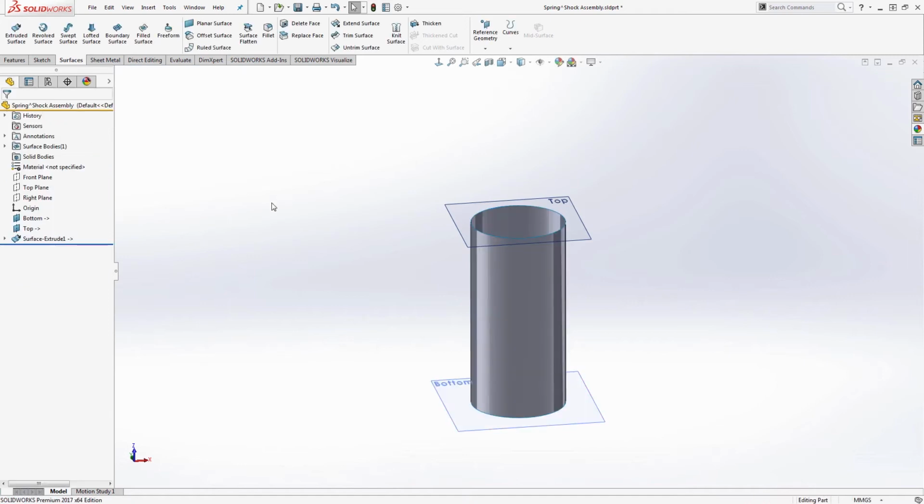Now at this point, it still doesn't look like we've done much of anything because we haven't. But what we have created is this adjustable height cylinder that will move up and down and scale. And we can intersect this with something that will give us some kind of reference that will shift up and down. And that's exactly what we'll do here. In order to create this geometry, I'll actually create a sweep that creates the helix itself. This is really the crux at this point of the surfacing trick. So let's create a couple of sketches here in order to make this work.